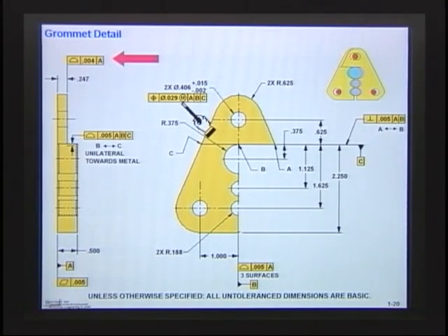Okay, next what I did is I applied a profile tolerance on here. You see that was my datum back here, that back face, and I said that was 247 away, and then I applied a profile tolerance, and I said that surface has to be profiled within 4. Now if that's profiled within 4, you know what that does is it's really doing something like this. I have a profile tolerance, and my profile tolerance, well, first of all, this is my datum. The datum is this face back here, right, that contacted on the high points. Not too good at straight lines here. And then it says profile within 4.